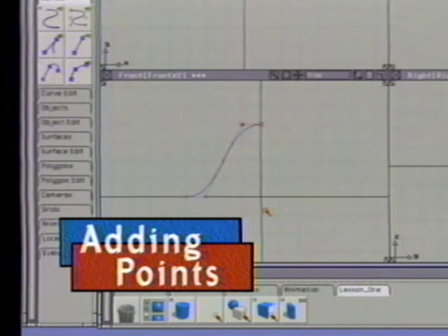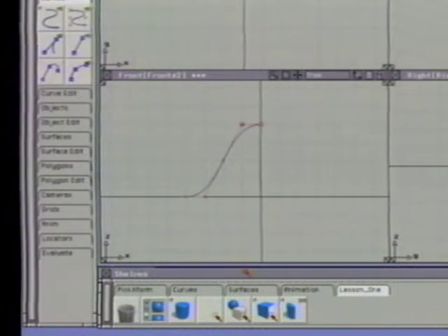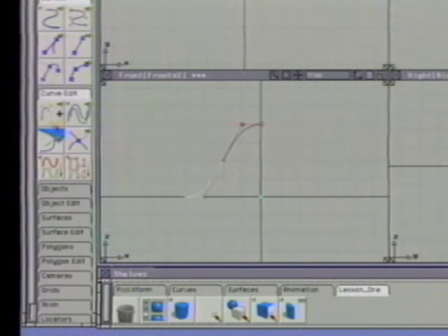Often you'll want to continue to work on a curve that has been deselected. Because the sombrero profile still needs more shape, you can add another 2 CVs to it. Select Pick Point Types CV in the tool palette. In the front window, click on the End CV to make it active. Now the CV is highlighted, as well as the end segment of the curve.